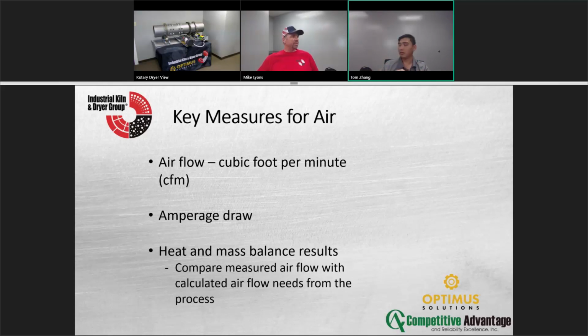Just a few, if you've got any examples of what could cause a big drop like that, going from 60 to 40? Oh, the easiest one is your baghouse plugging, or some kind of dust collector plugging, because there's so much pressure that you can blow the bags. So you would actually lower that to relieve the pressure a little bit and then go back up. So a pluggage. Have you ever seen anything like a damper? Yes, you could close that damper and it'll raise or lower your CFM.